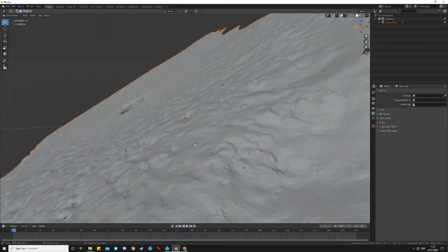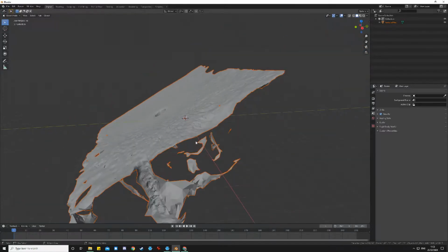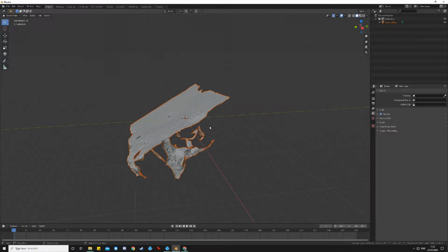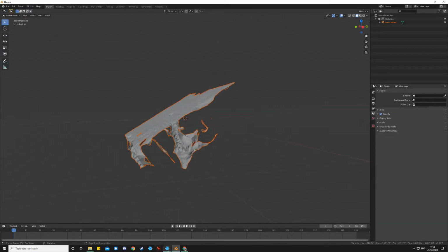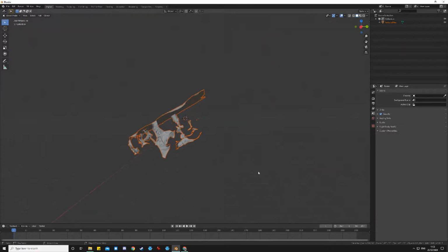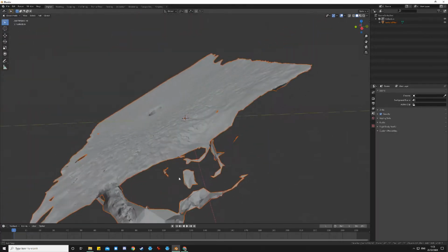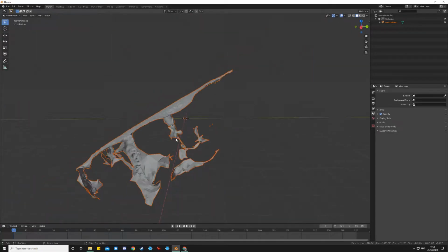And there we are. And you'll see, oh, that's a bit of a weird shape. Well, it's because if we zoom out using the mouse wheel, you'll see that it is the same object, it's just upside down. This is because Meshroom doesn't really know which way is up. It's able to extrapolate the difference between the different parts of the picture, but it doesn't actually know that the ground is the ground and the sky is the sky. So you have to right it the correct way around first.